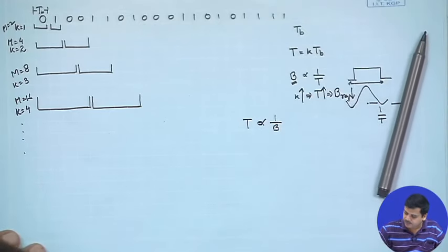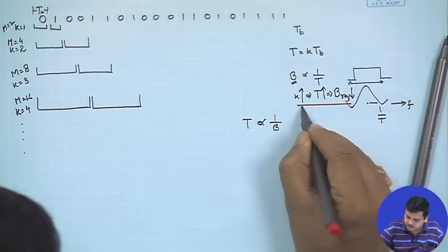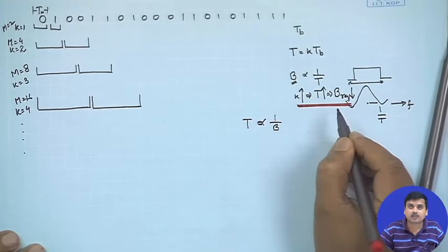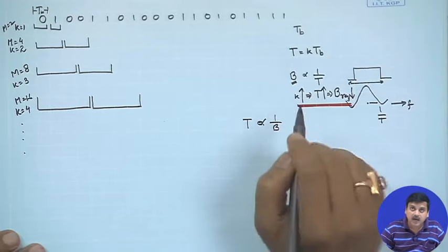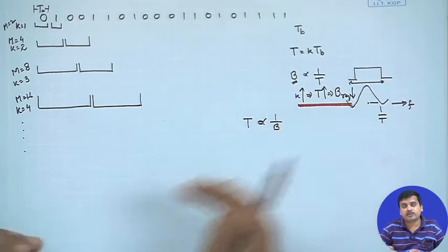This is important. Okay. The other view is, so what is the summary? The summary that we are trying to say is that if I am choosing a higher order modulation, every time I send a waveform, I am actually sending more number of bits. For example, if I am choosing one of 8 possible levels, I am communicating 3 bits. If I am choosing 1 out of 16 possible waveforms, I am actually communicating 4 bits. So, this is the notion that should be with us.